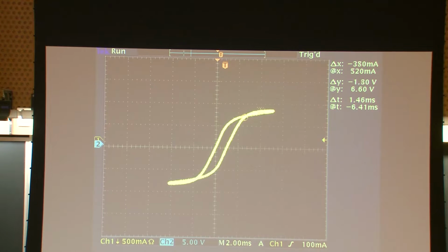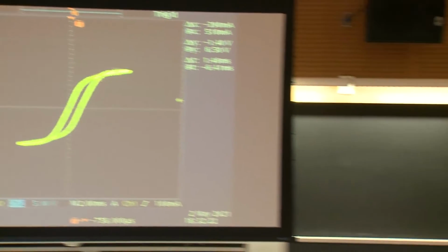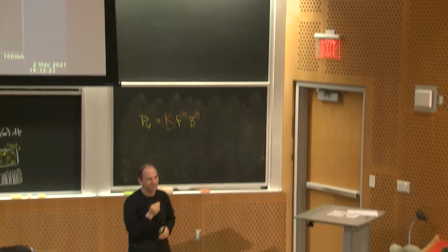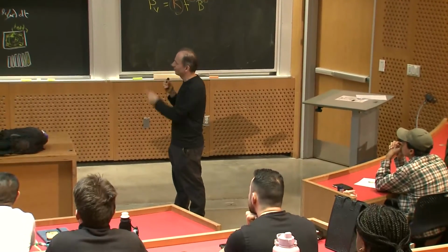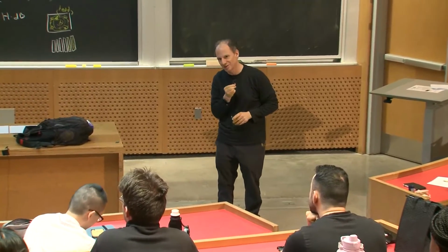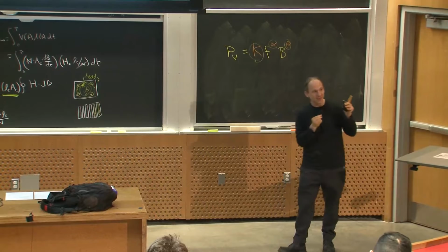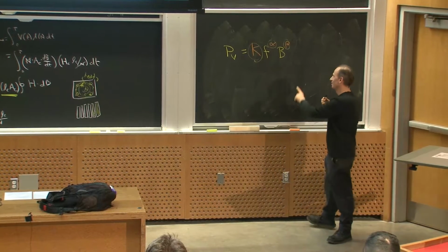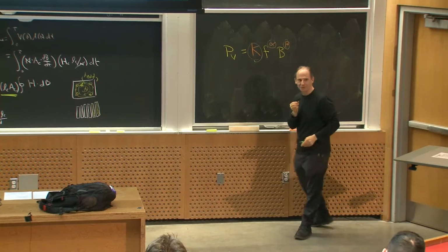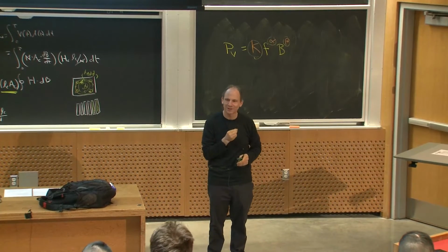No. So there you can see, based on the earlier calculation we did, there's this hysteresis loop between B and H. You would see that it changes shape versus frequency. That's what a real core material looks like, even though we pretend it doesn't do that. So all you've got to do is be careful. If you're going to have a lot of AC flux density, figure out your loss per unit volume and use it. So that's my very hand-wavy introduction to loss in magnetics.